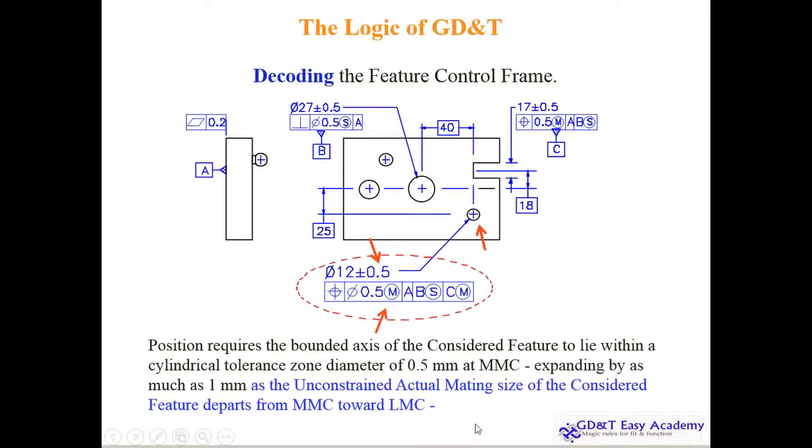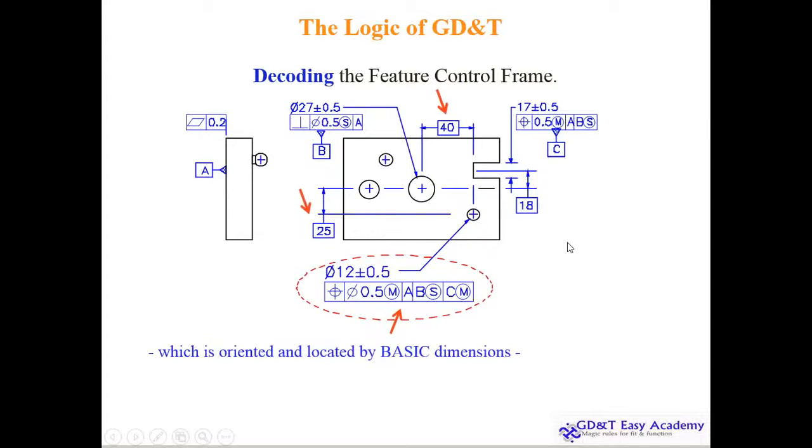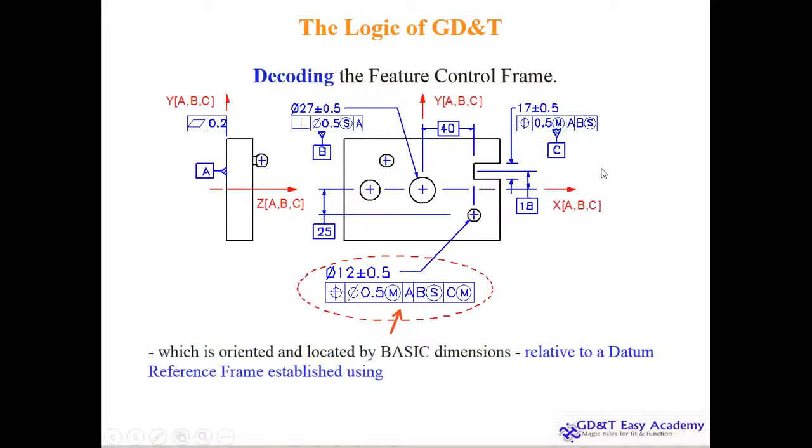And you can see the departure of this particular condition because of the collective effect of the dimension tolerance and geometric tolerance for controlling the orientation, position, size, form control is now addressed. So what is the orientation of the basic dimension? So if you see the basic dimensions 25 and 40 here, they are critical, relative to the datum reference, because we have keyed our coordinate system here.